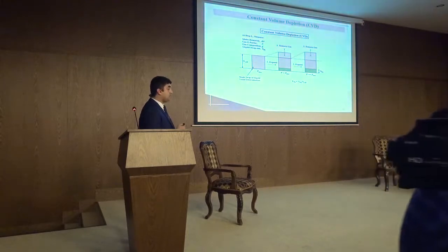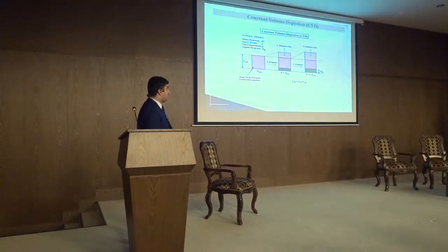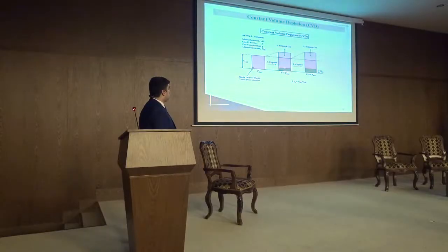By using the constant composition expansion test, we define the dew point, and we start our experiment at dew point pressure, and then we reduce pressure, and you see that after reduction of pressure, the gas expands and we remove gas. And we define gas formation volume factor, liquid dropout, relative volume, gas viscosity for all pressure steps.